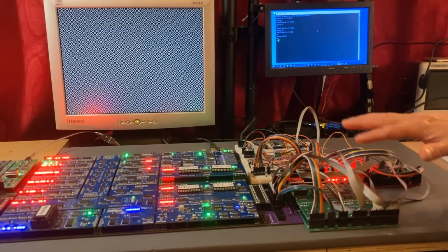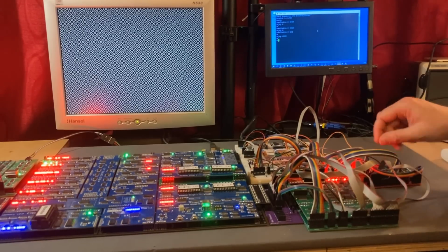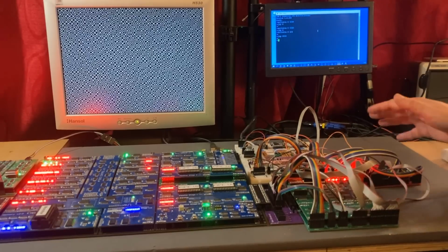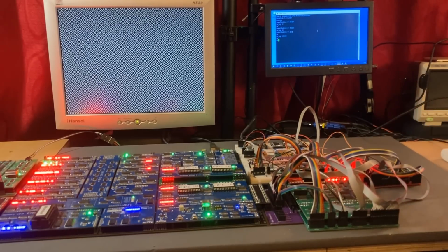Tell you what, when I do a kind of next generation build, I'm going to consider putting power connectors in which are keyed so you can only put them in one way. It's not going to solve every problem, but it would have saved me here. I feel we got lucky with the power there, but apart from that, the circuit worked first time. I'm probably storing up some bad luck for future problems, but let's ignore that for now and be grateful that it works.